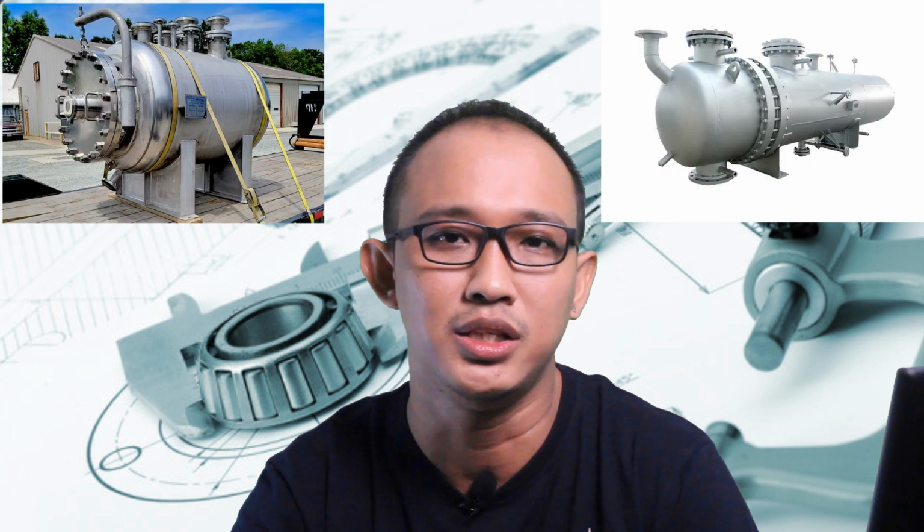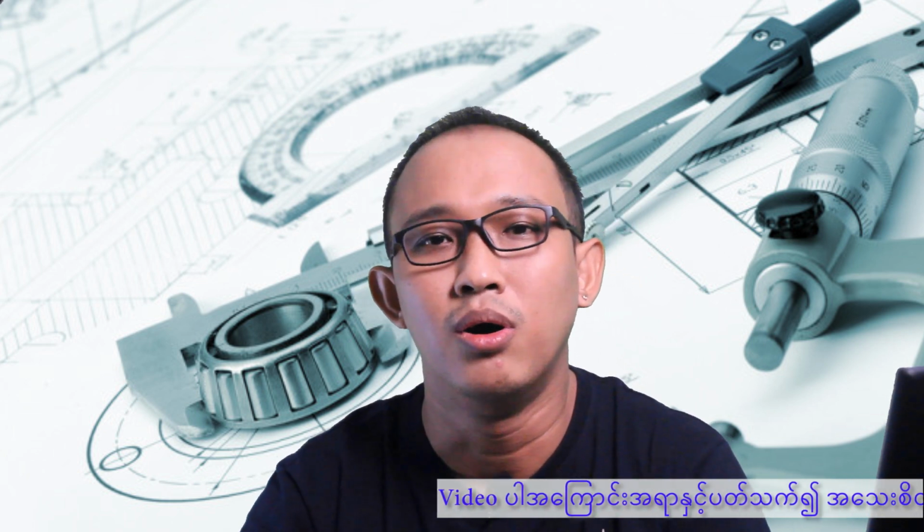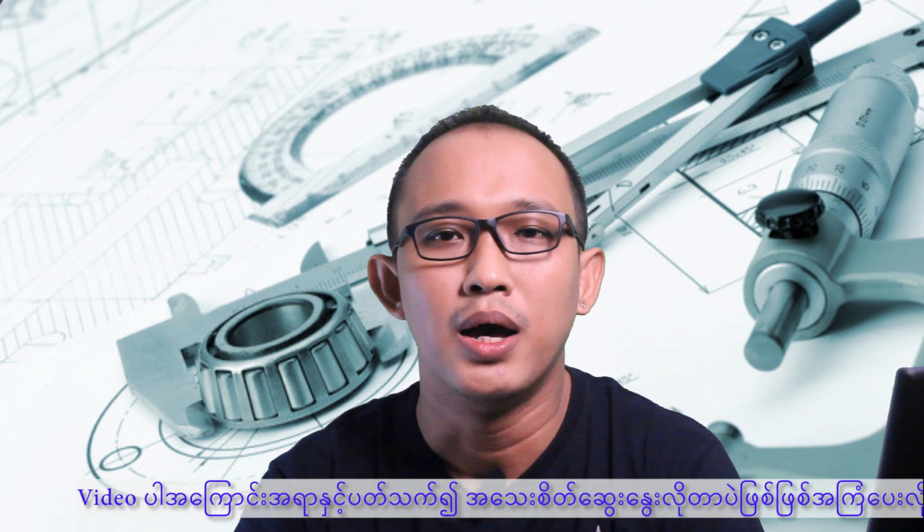Let's continue about flanges. These flanges are used on the nozzles of pressure vessels, heat exchangers, and piping connections. These flanges are used not only for attachments of another pipe line, but also for instrument attachments. For example, an instrument-only nozzle, like installing with a safety valve, pressure gauge, transmitter, etc. On the other hand, there will be inlet-outlet connections and drainage nozzles, which are connected to another pipeline.